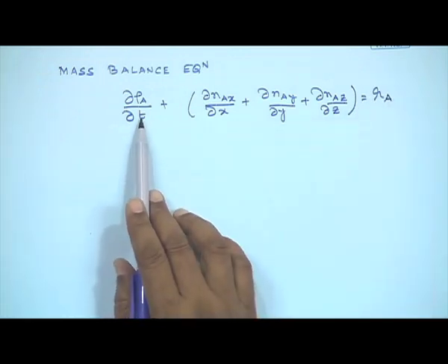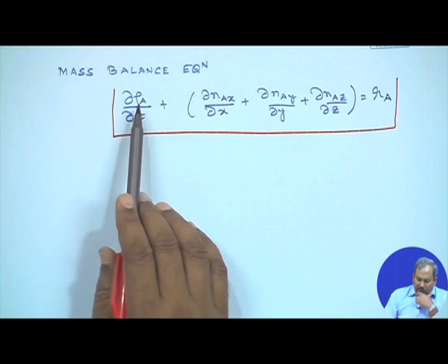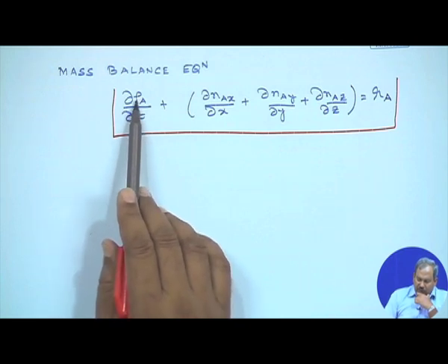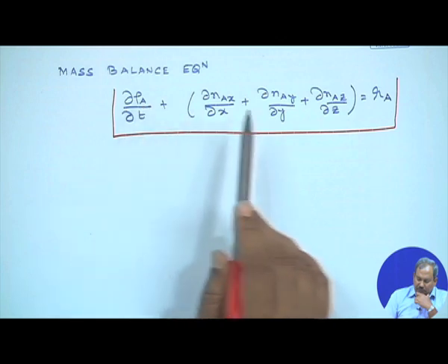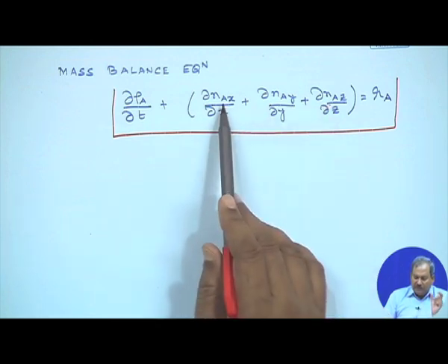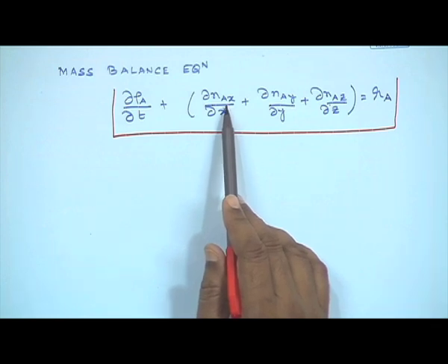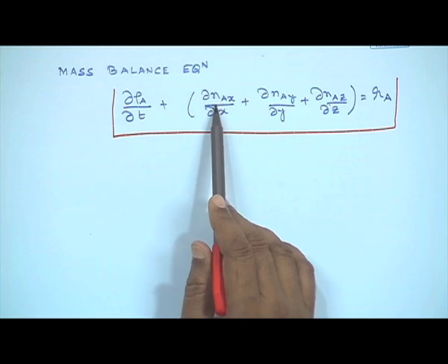So, this equation then is the species balance equation, where this gives you the time rate of change of mass concentration of A inside the volume element. These three are the net rate at which the species is being added to the control volume. But we underscore that this N_A will have two contributions: one contribution from the diffusive mass transfer, the second from convective mass transfer.